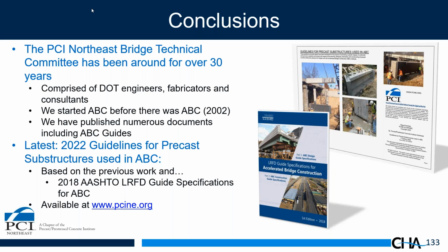Okay, we had a lot of questions about joints. We'll get into those in just a second, but there was one here I wanted to ask you. This came in during the presentation. Are there any successful examples of use of a precast pier cap with a secant pile wall to allow for accelerated top-down construction? The secant pile wall would act as the abutment wall. I have never seen it happen, but I can see how you could do it. You could have a secant wall with dowel bars projecting out of the top of the secant wall, and you could set a precast cap with corrugated pipe voids. You could definitely do that.